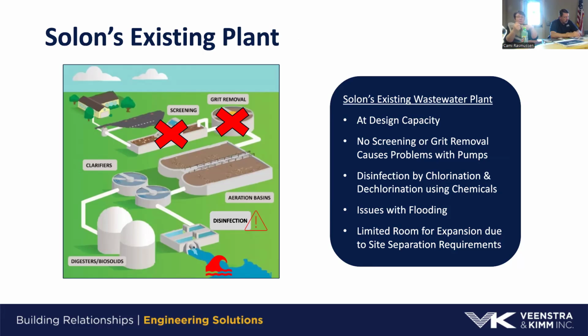And then in this diagram, we've got the disinfection shown, but the one shown there is ultraviolet. What Solon is using is chlorination and dechlorination. So they use gas chlorine and sulfur dioxide to chlorinate and then dechlorinate so that it's safe and you're not killing anymore. Just from a handling standpoint.